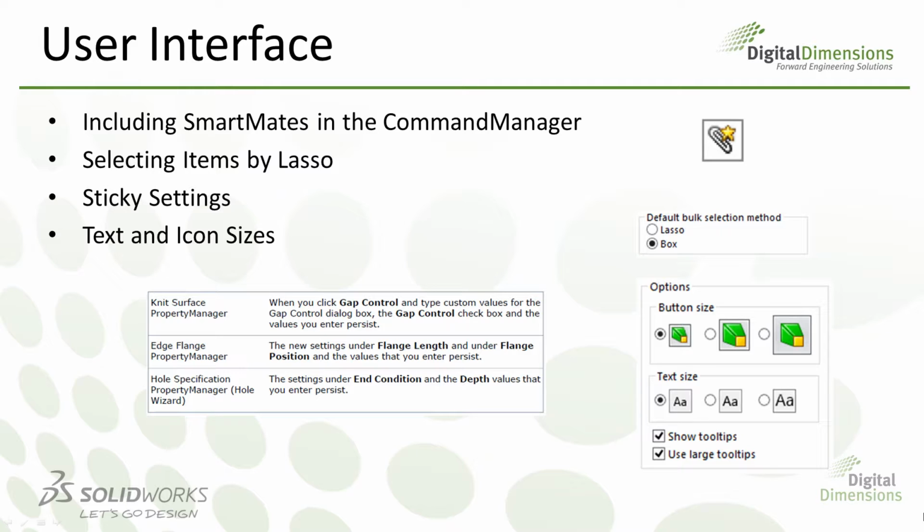And I put a few examples of that on this slide, the knit surface property manager, the edge flange. A lot of these things, the next time you open that command up, even in the same session, it totally forgot what the settings were for the previous item if you repeated that command. So you'll notice in 2014 a lot more stuff remembers, even between sessions of SOLIDWORKS, what those settings were in the property manager.